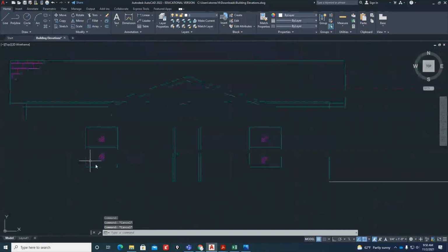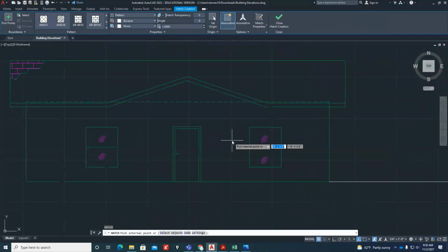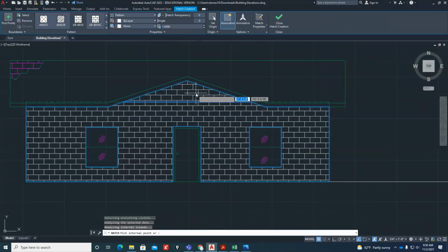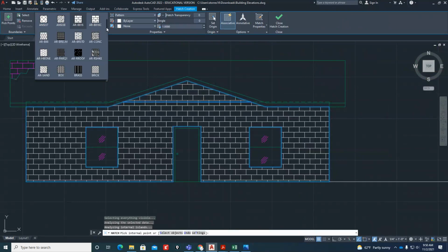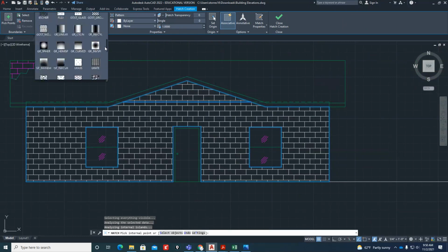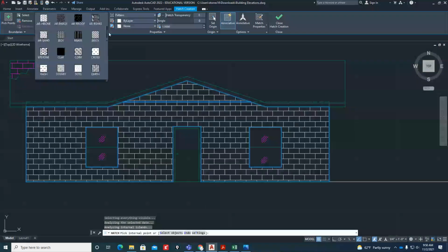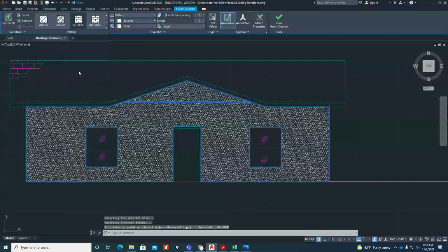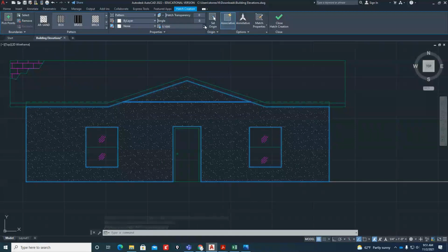And then as far as the stucco pattern that I want you guys to use in this area here and here, of course, if you're on a brick house, it would look like that. But what I'm going to ask you for is stucco. And the pattern we usually use for stucco is called sand. There's an architectural sand pattern, if I'm not mistaken. There it is. Except not that dense of a pattern. Let's go with maybe a 5. Let's see what scale looks good.